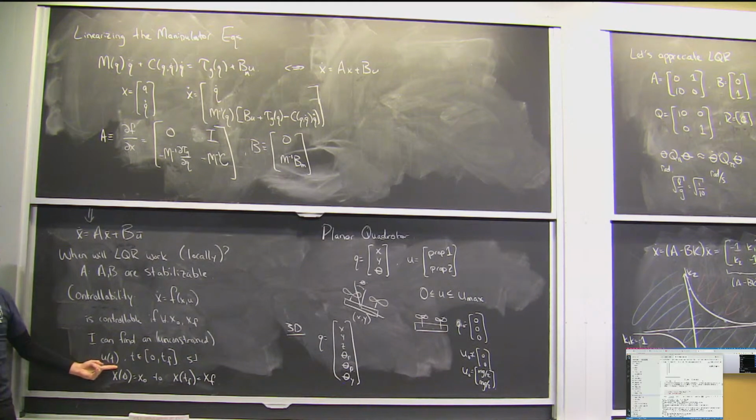And it happens that there's a check that's very natural, based on the controllability matrix, to check this condition for linear systems. Okay? In Drake, there's a function called controllability. You can pass it the A and B matrices, I guess you have to pass it the A and B matrices, and it'll give you back a controllability result. You can either ask it, is it controllable, true or false, or you can ask it for the controllability matrix. Okay?